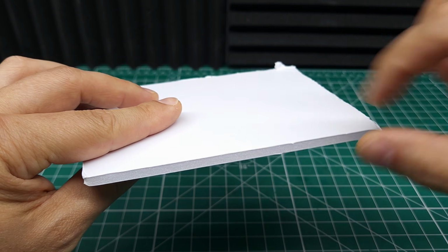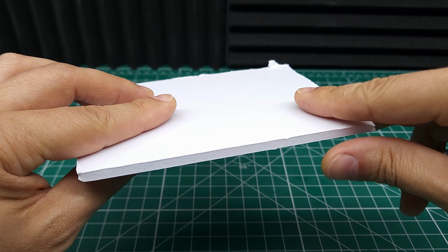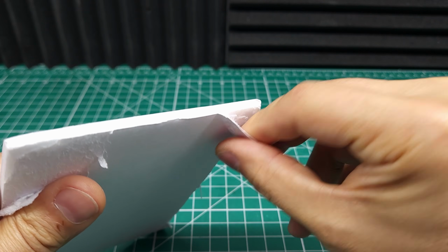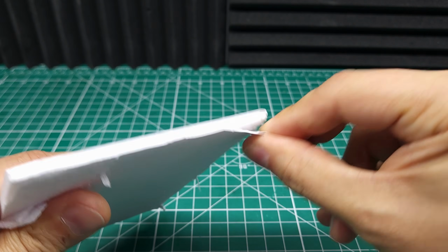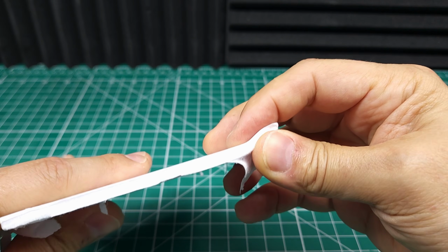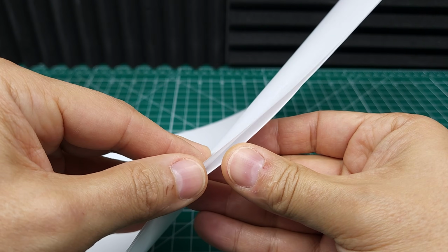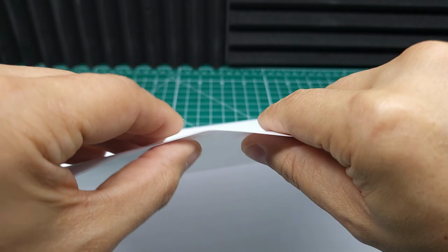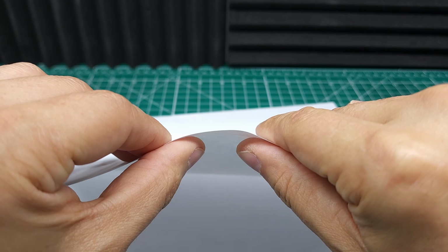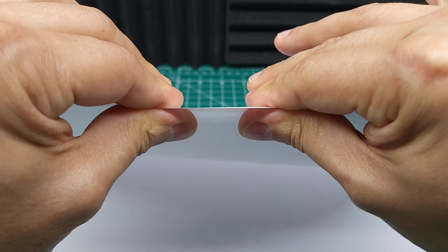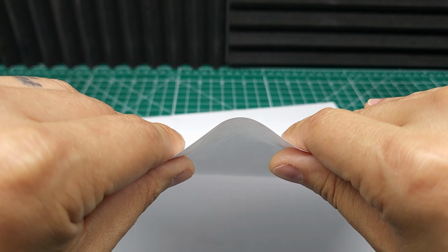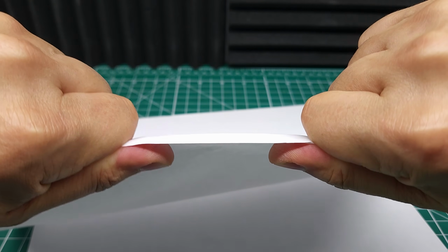This is basically just two pieces of paper glued to a piece of foam in the middle, but it's actually very strong in bending. However, if I rip one of these pieces of paper off, you can see it's very floppy and bends really easily. The foam in the middle also bends fairly easily. And that's because the piece of foam is actually taking the two pieces of paper and separating them. So instead of the paper just bending like you see here, the paper on top tries to stretch when you bend it, and the paper on bottom tries to compress. Of course, paper isn't very strong in compression, but it is very strong in extension.